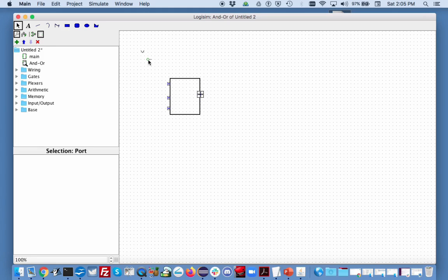Notice that when you try to select the output pin, instead you select a green circle with a line in it. This is the anchor point, which will be used when you drag the subcircuit, and the point about which it will revolve if you change the direction of the subcircuit. I usually place this in the center of the subcircuit.